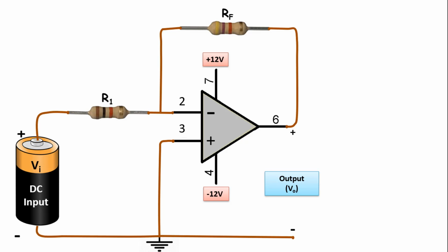So, how do we find the output value? If we show the input value Vi and the output value with VO, VO equals negative Vi times RF over R1. If you ask where we found this, a Kirchhoff voltage law is written at the input and a Kirchhoff voltage law is written between the input and output. Since the currents are equal to each other in these two equations, this equation comes when you replace each other. If you wish, you can look at how it was found later from another source.